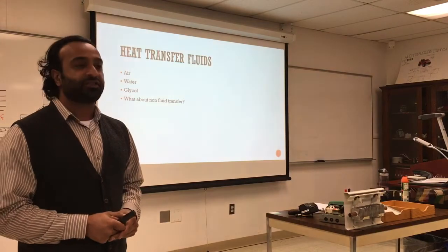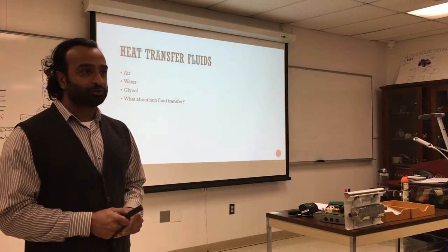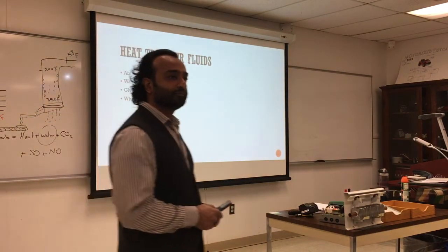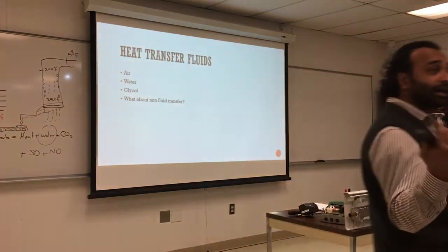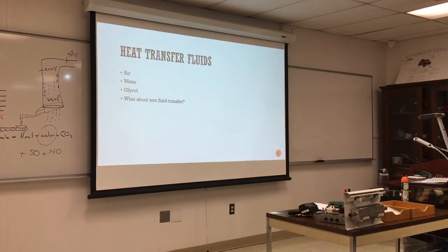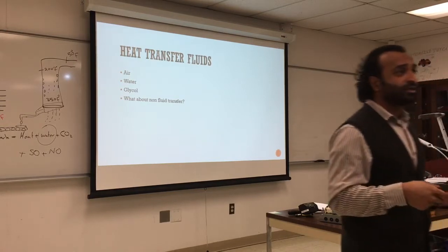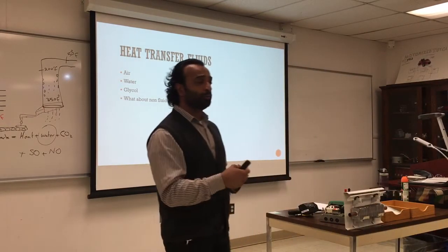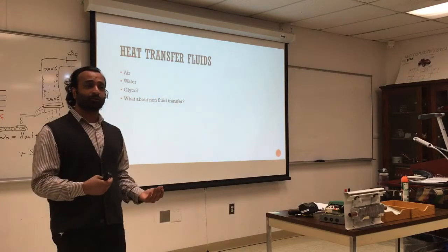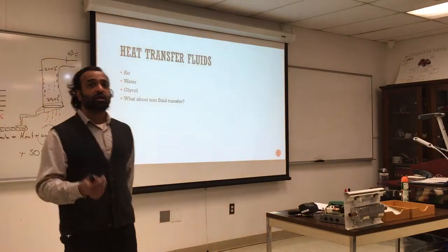They can use oil, synthetic oil. There are some kind of synthetic oil you can use, just something to heat up the closed loop. It is heat transfer fluid. You can use oil, synthetic oil mostly, because it does not react with the pipes. And also you have to have some kind of a match between the pipe material and whatever fluid you put into it, otherwise it will rust.